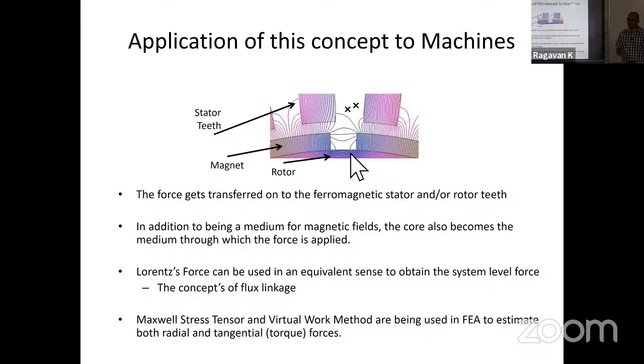Yes, sir. But is there any chance that the field will interact with the winding? That will create a hotspot in that winding because of the concentration of the field outside those insulations for each and every conductor. Okay. You're saying, are there additional loss related effects in a slotless case? Yes. I don't know about the insulation part. Is there any issue?